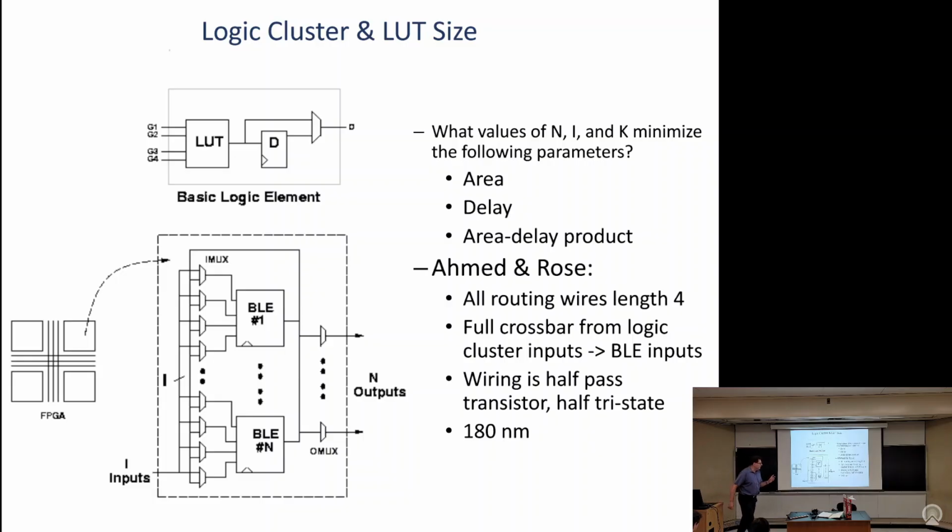Okay, so that's delay. Area, it's basically that minimum width. Inside VPR, it knows how to build essentially transistor level circuitry, just for the purpose of area estimation. So it basically asks: how many switches did you ask me to build? How many SRAM cells is that? What drive strength did you say they are? And it'll build all of that stuff, and then tell you this is how much area, in these minimum width transistors, your FPGA takes. So you can use that to compare one architecture A to B. Does that make sense?